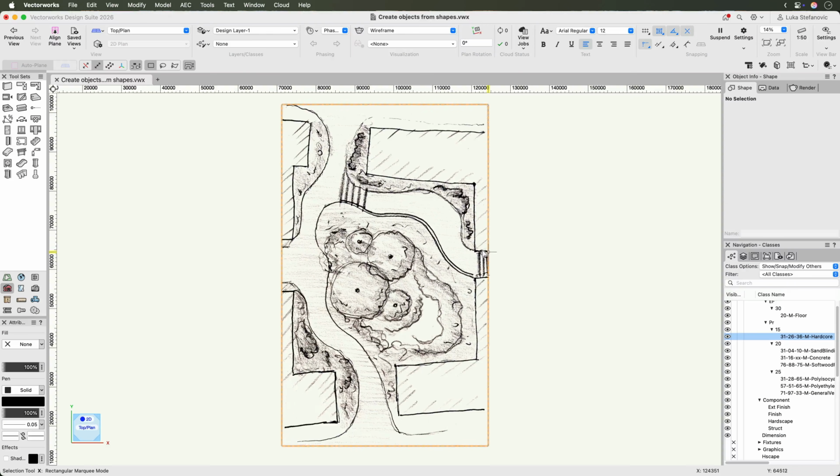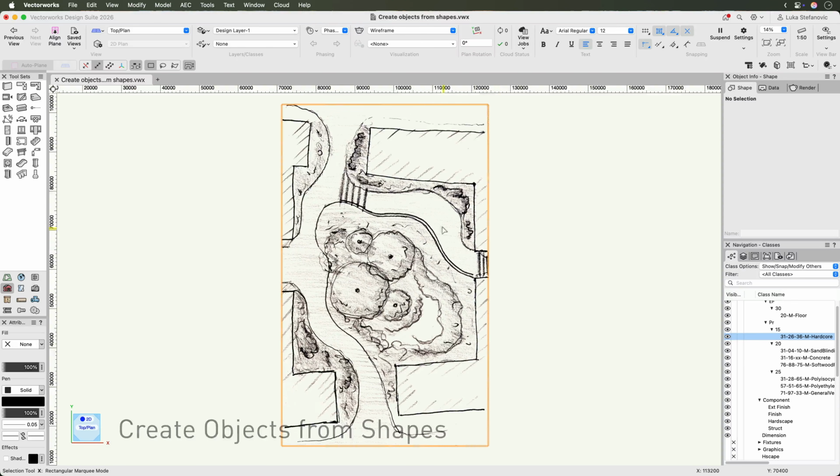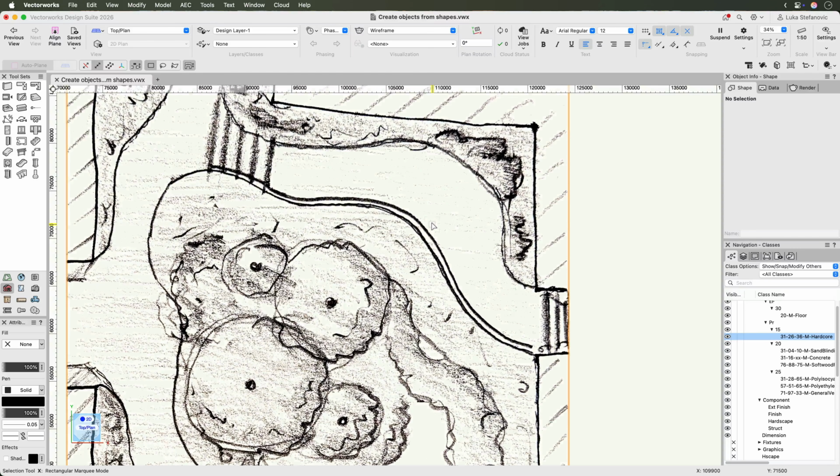Let's start from a familiar place. A hand-drawn plan that's been imported as an image, scaled to correct size, and then we can trace over some lines and polygons. No styles, no data, just simple geometry. I've got where I want the railing to be traced as a polyline, following the curve from the hand sketch. It's easier to trace these kinds of shapes if you temporarily pause the snapping by holding the tilde key.